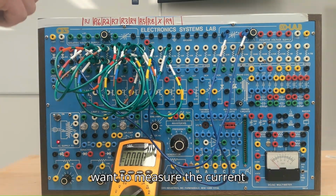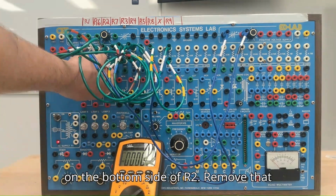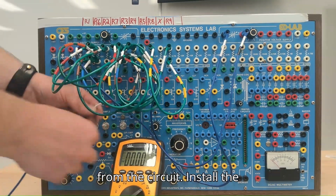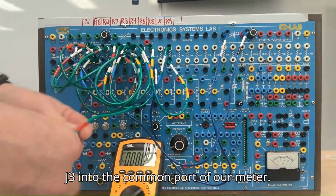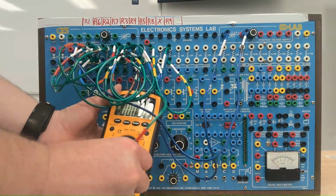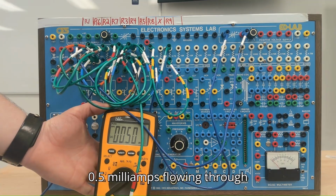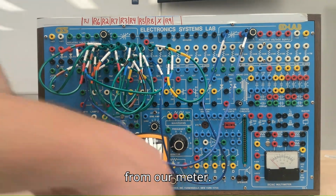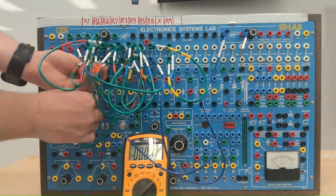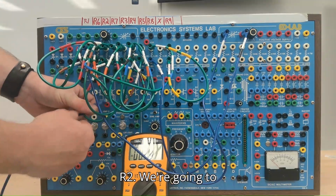Now we want to measure the current through J3. J3 is on the bottom side of R2. Remove that from the circuit. Install the temporary test lead in its place. J3 into the common port of our meter. We have an amperage reading of 0.5 milliamps flowing through J3. Okay, we're going to install jumper 3 back into the circuit. Remove it from our meter. Remove the temporary lead. Put jumper 3 back into the bottom side of R2.